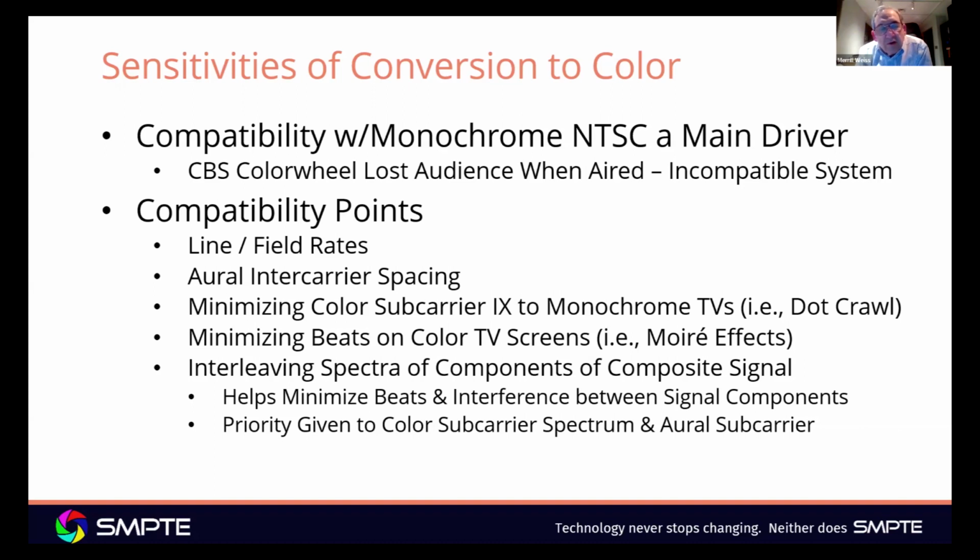So the compatibility points that are of concern were, first of all, the line and field rates, the spacing between the aural signal and the visual carrier and the color subcarrier in particular, minimizing interference from the color subcarrier into monochrome TVs, which was seen as dot crawl.